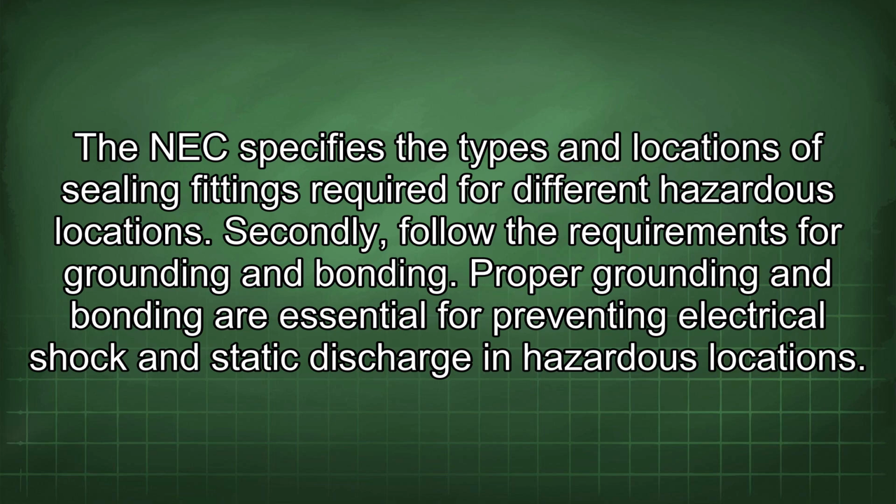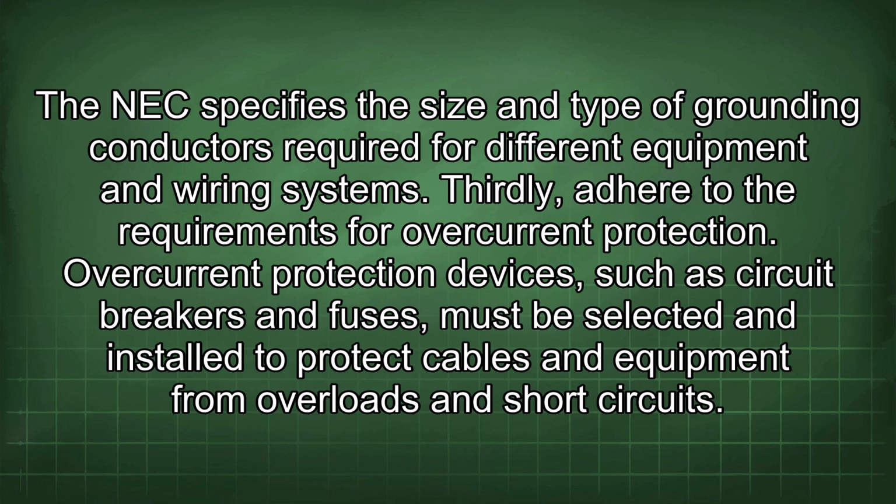Secondly, follow the requirements for grounding and bonding. Proper grounding and bonding are essential for preventing electrical shock and static discharge in hazardous locations. The NEC specifies the size and type of grounding conductors required for different equipment and wiring systems.